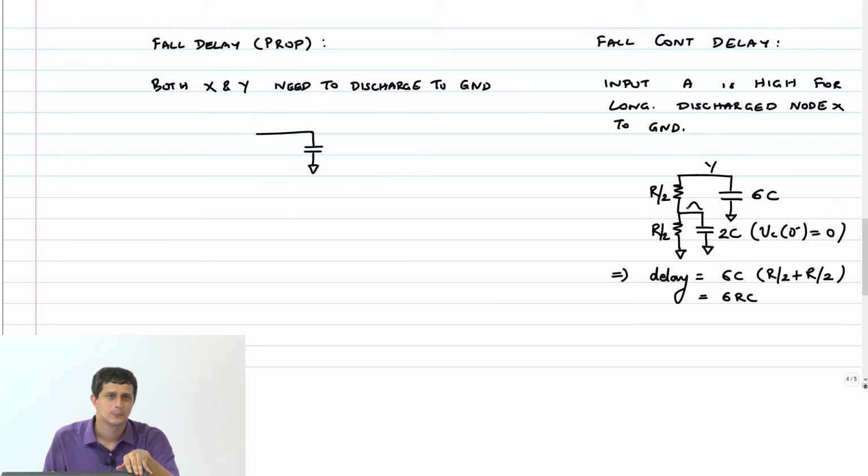So her question was, if this capacitance was already discharged to ground, that means the VDS of that bottom NMOS transistor is 0. So how can you have any current flowing through that? She is right, because to accommodate some current, the VDS has to bump a little bit. Only then you can have some current.